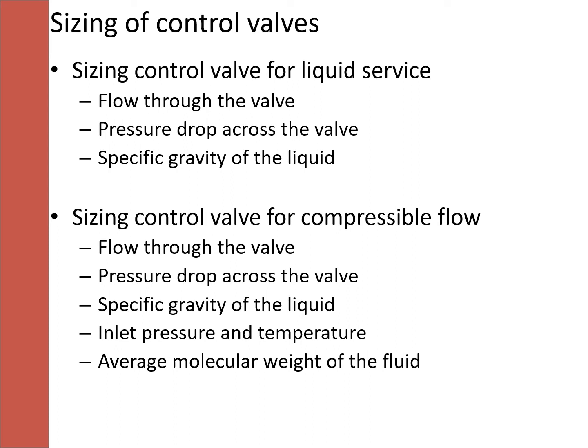Now we move to the sizing of the control valve. For sizing a control valve for liquid service, there are 3 criteria that need to be fulfilled, which are flow through the valve, pressure drop across the valve, and lastly the specific gravity of the liquid. So this is the sizing of control valves for liquid services.